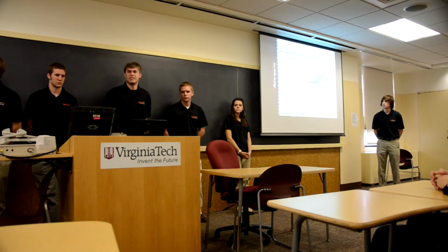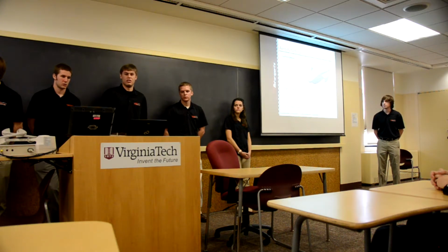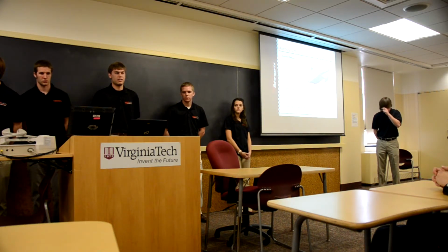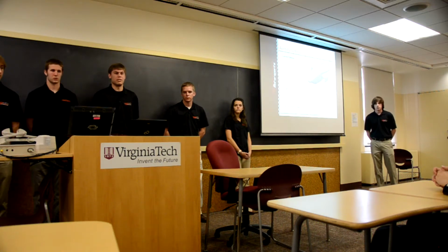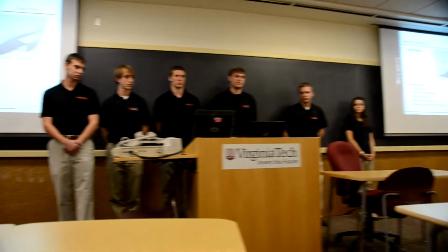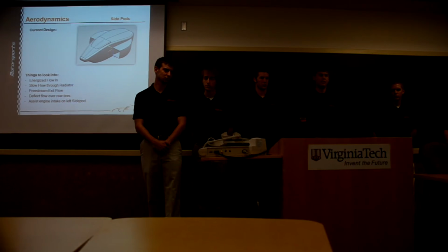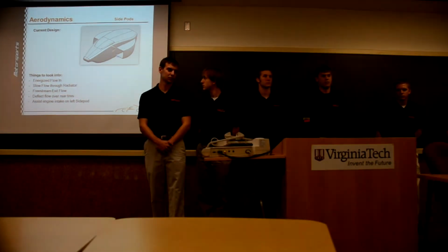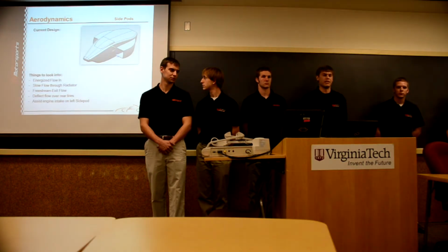I'm also working on the side pods. We don't have very much done as far as design on the side pods right now, so that's going to be our next big step. We really want to get the best flow, a lot of energized flow coming into the side pods, slow it down to the right speed. We need to talk to the engine guys, figure out what flow rate they want going through the radiator so we can determine the size of the side pods.